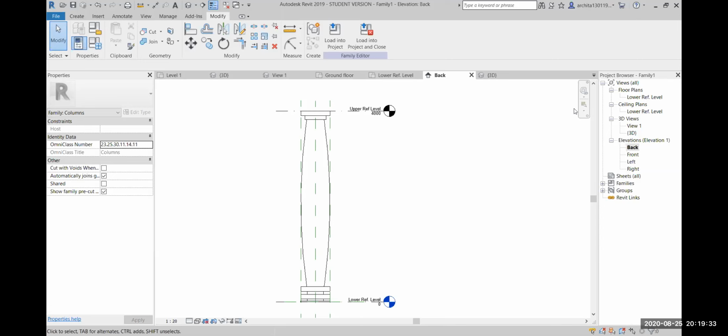Maybe I'll just record it and send it to you. Fine, but listen to what I'm doing. I'm making the work planes. I'm creating the sectional profile. That's what I said when we were making the work plane. Remember, we had discussed that we can create the sectional profile in each and every work plane and then create an entire form out of it. So think of how the sectional profiles will be there. Move the sectional profiles here and there so that a form can be generated.